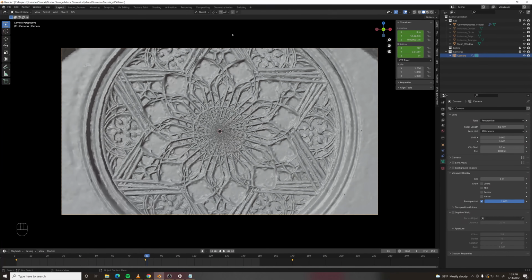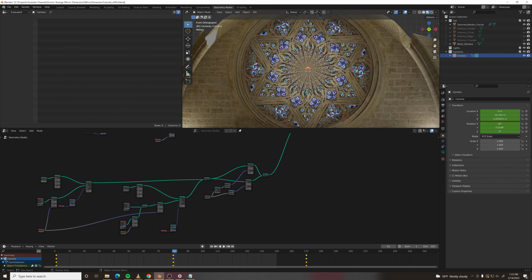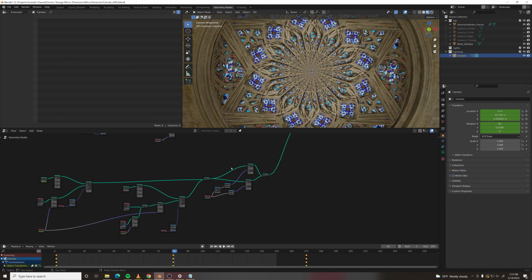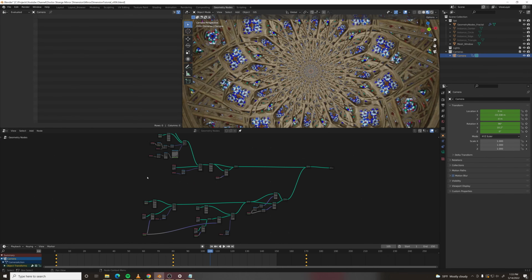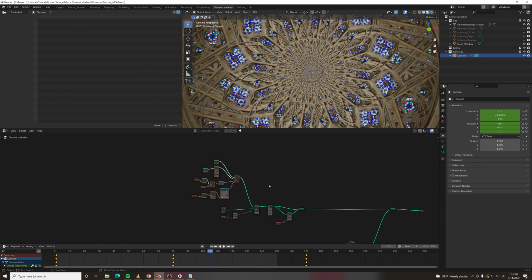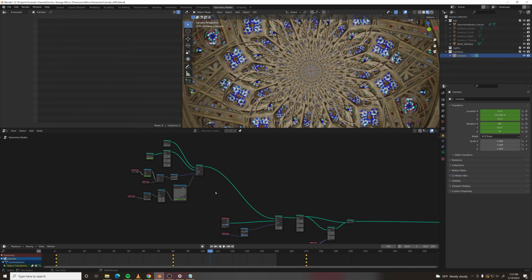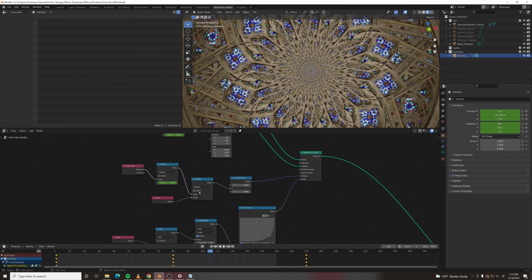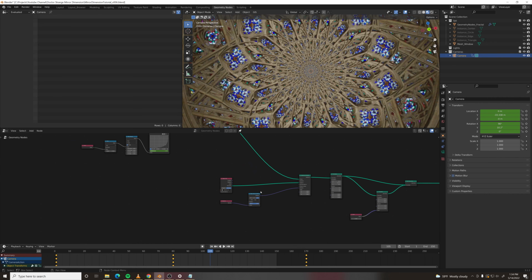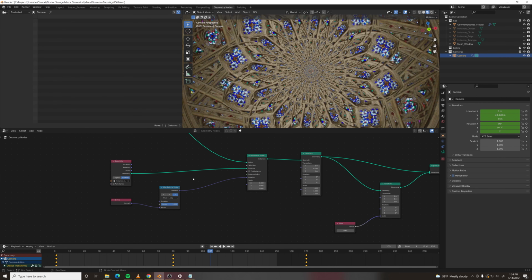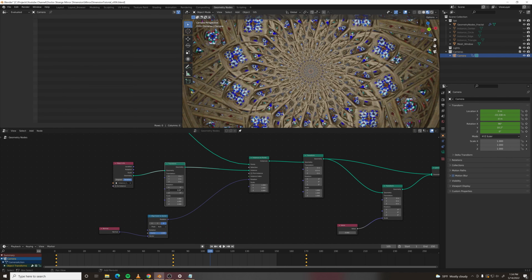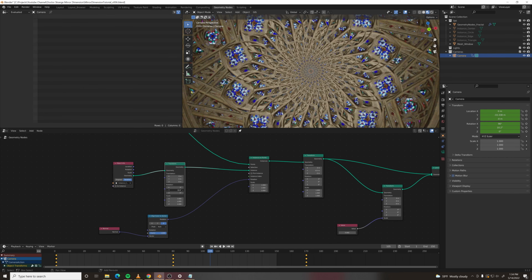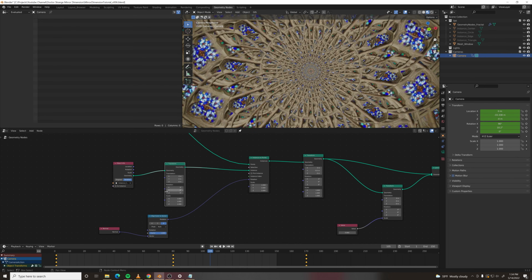One more thing we can do if we hop back into geometry nodes is we can rotate these center instances individually on their axes, which adds a little bit more flavor to our cocktail of random fractal stuff. So if we go over here to the center and we find our center instance, let's make a transform, plug it in, and if we rotate on the y-axis, we get this interesting spirally shape happening.